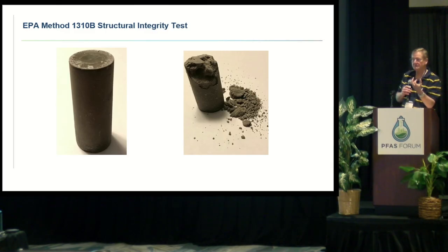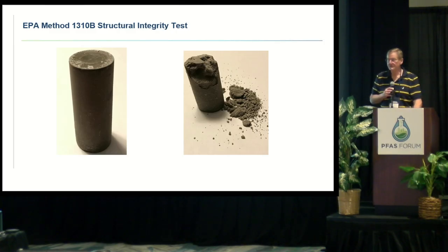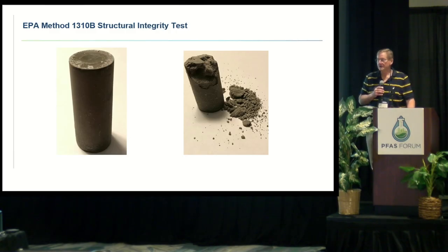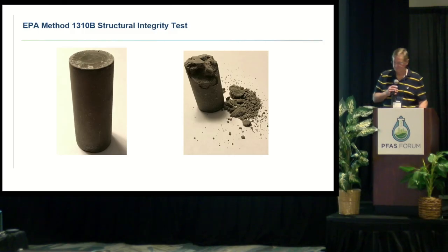Not one of them. Nor have I been to any of those 500 sites that is exposed to the full range of the pH scale. But it is rained on. It's going to get rained on. If you do in situ stabilization, it will get rained on. So my argument has been, and it's seemed to hold up, is that the SPLP is probably the best way to demonstrate leachability.